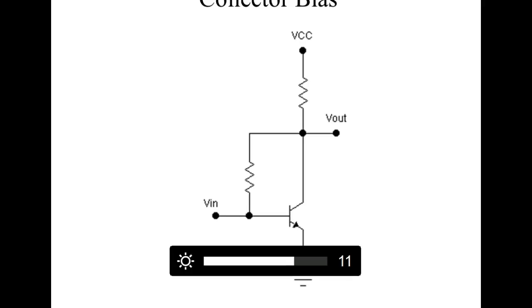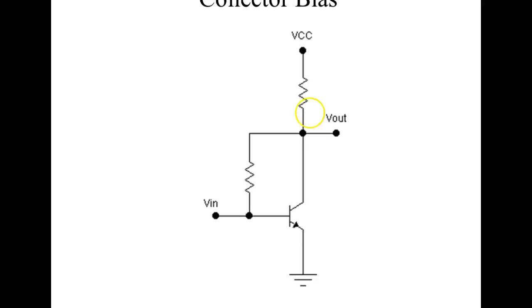So we set up our bias basically the same way. We want this to be sitting at 3 volts. Now it's working great. It's going to be sitting at 3 volts. Are we okay? And then I would size this resistor to drop 2.7. So a while ago we sized it to drop 4.7 volts, right? Now, if we're going to set this at 3 volts, I would calculate my collector current, so this would be 6 volts, and then I'd say, okay, what current do I want? Let's say we want 1 milliamp. Then right here, I would set this for a 3K resistor. So a 6K would drop all of it. A 3K would do what? Drop 1/2. That would set this at 3 volts right there.